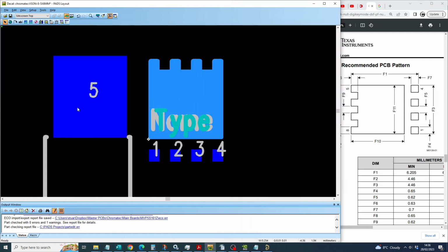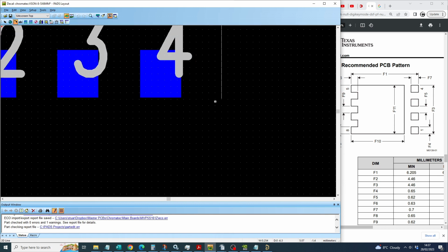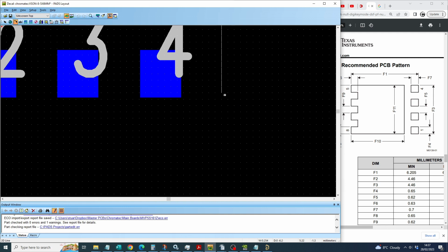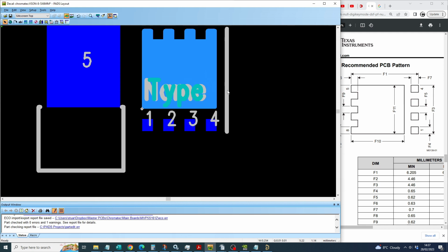This is worth noting. If the options in the drafting toolbar are place 2D line, you'd think it would be 1D line, wouldn't you? So we start off with a 2D line, and we're going to put it at the top of the castellation all the way down to the bottom. We want this to be a bar. If we click on this, it will just disappear because we haven't formed the 2D shape. And if we right mouse click, we can select path. You can see I've done this already. If we select path, then when we double click on it, we have the shape that we require.